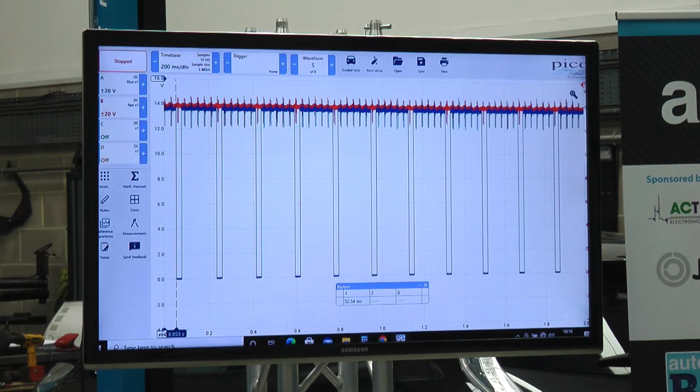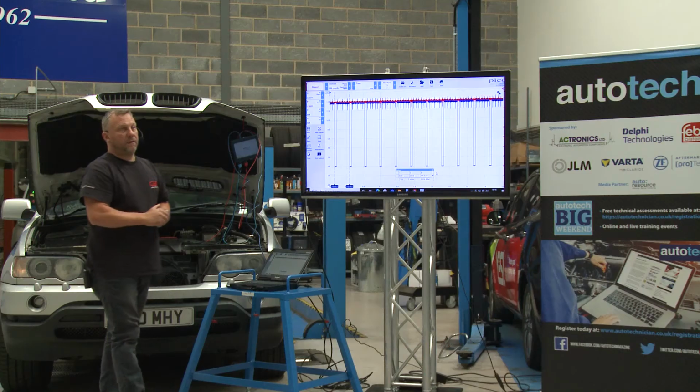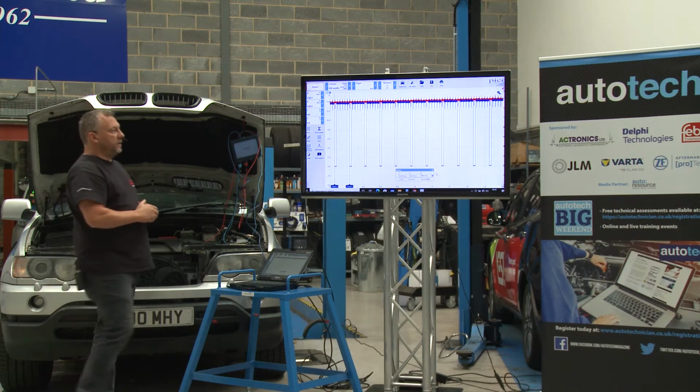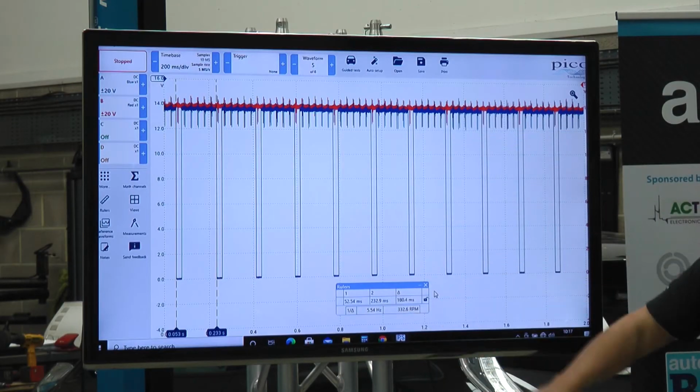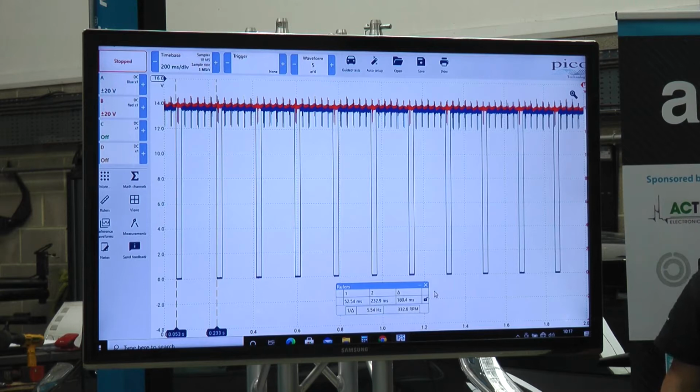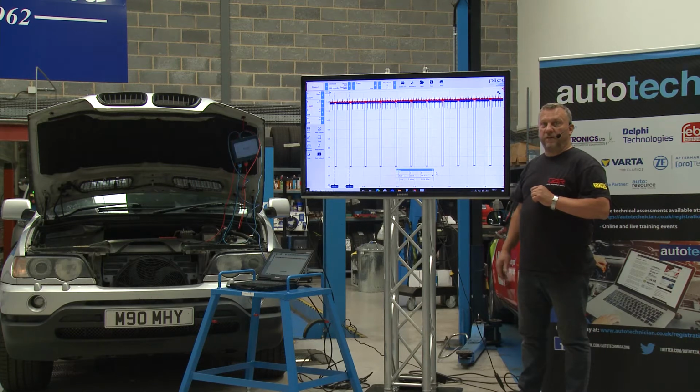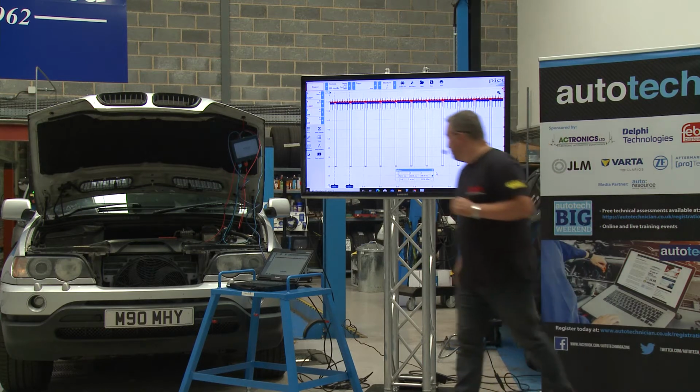So ruler 1, and then ruler 2. We can see the delta, represented by the triangle, is 180.4 milliseconds, which is converted conveniently in the ruler's box to 332.6 RPM, or around about 664 engine revolutions of the crankshaft, remembering the camshaft is at half crankshaft speed.